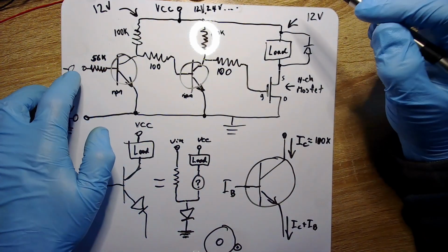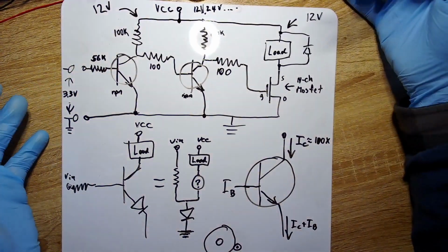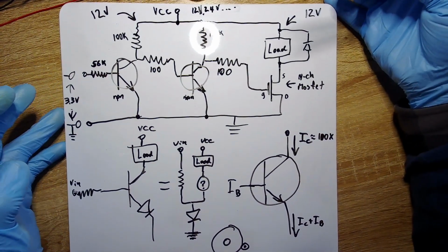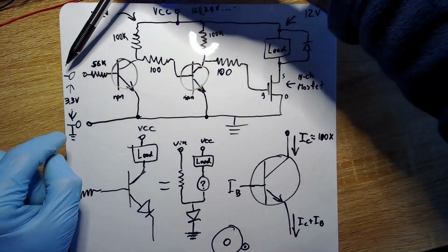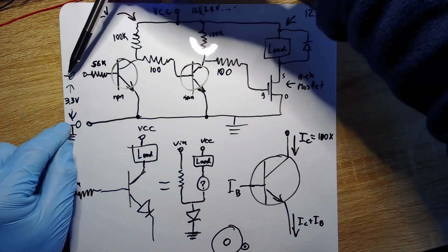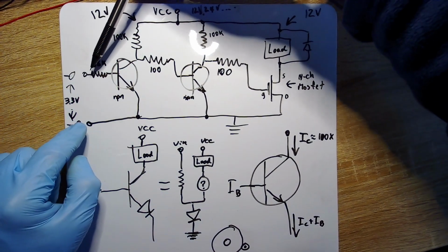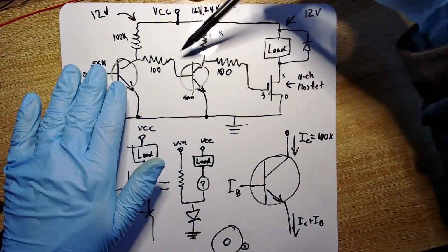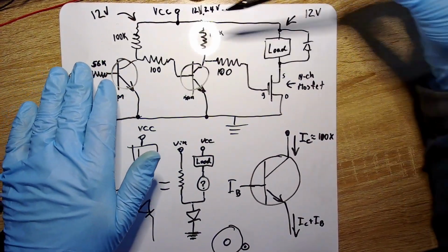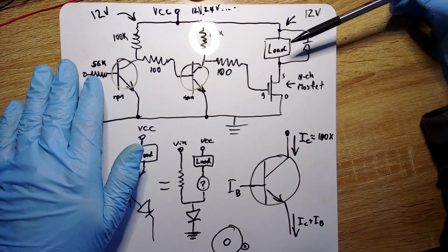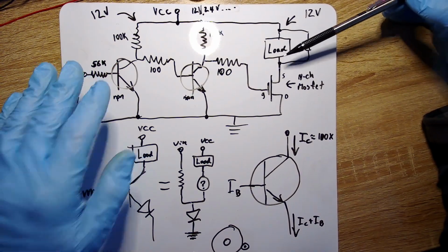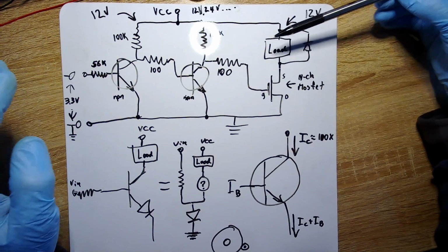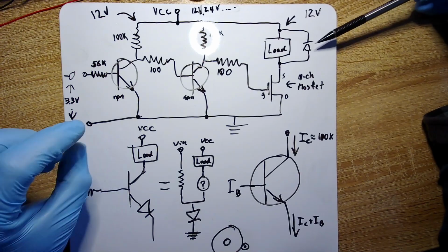But if you can get in there and you can look, and I've seen Diagnose Dan do this. It's beautiful. Goes on the board, finds the computer. You can see the voltage going up and down here. And right here, because it's an impedance, it's separate. But then over here, something isn't working. This load is not working. I think it was an injector circuit. And these are noisy, nasty circuits on a car. That's why these flyback diodes are freaking critical.